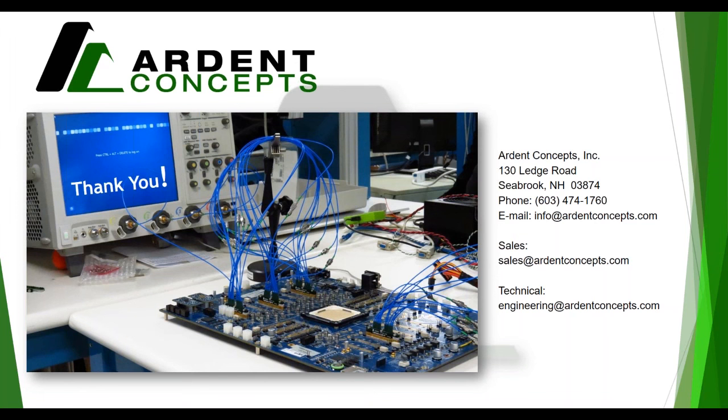But you can also do a through measurement, which is what we publish for data. We'll give you through measurement results on the board with a connector and an edge launch, either a 1.85 or a 2.92 edge launch. So we encourage you to verify your results either on that vehicle or, as I mentioned, put a coupon off to the side of your next design and just go to an edge launch connector. That way you don't have any real risk in it.